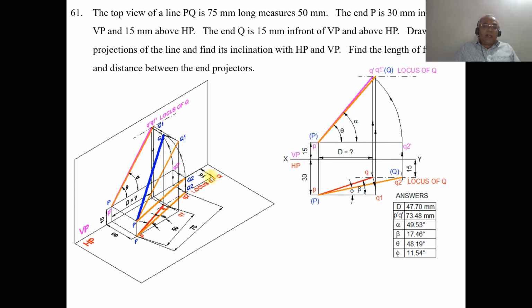So when you are projecting this onto the vertical plane, that means when you are looking from the vertical plane, what happens? The image will start rotating from Q2 dash on the vertical plane. With P dash as center and P dash Q2 dash as the radius, it rotates such that it will cut this end projector line, the end projector line of this line, that is, from Q dash you have a vertical projector. That vertical projector is the same as this vertical projector here.